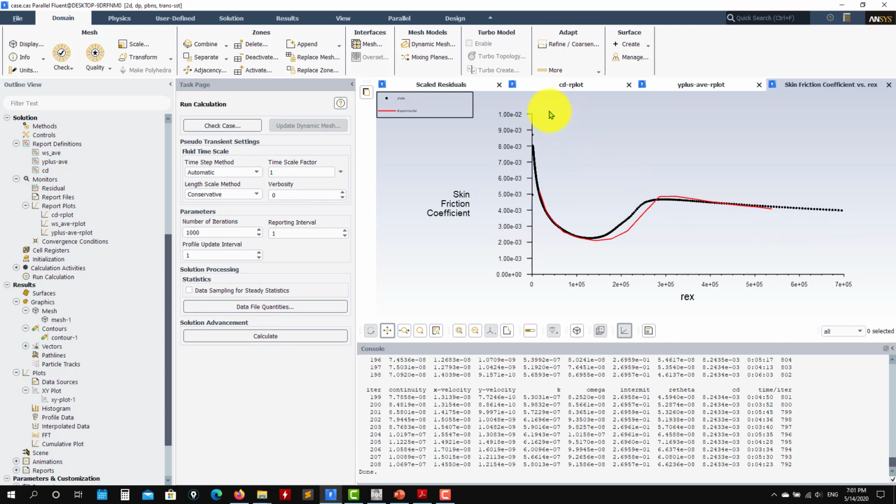If you run the SST, k-epsilon, and whatever other models, they will all resolve this part very well, but this area will fit here in the upper part, telling you that everything is turbulent, because all those turbulence models assume that your boundary layer is fully turbulent. But it was mentioned that let's rerun, but let's choose the turbulence intensity level at the inlet, and let's see what happens.